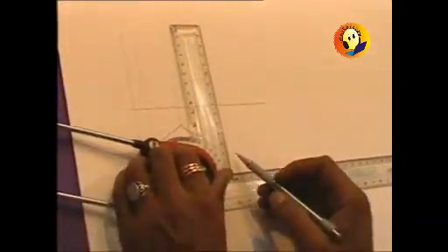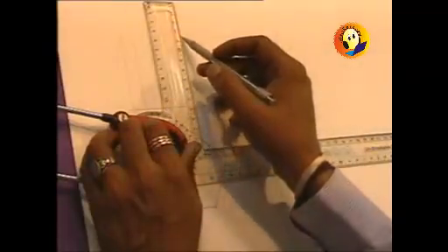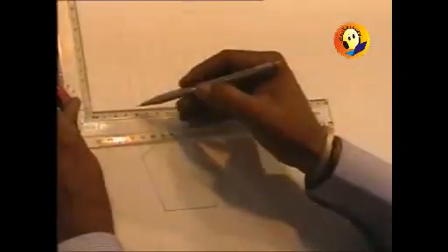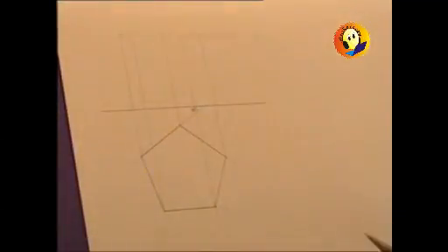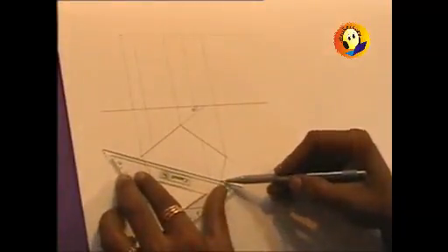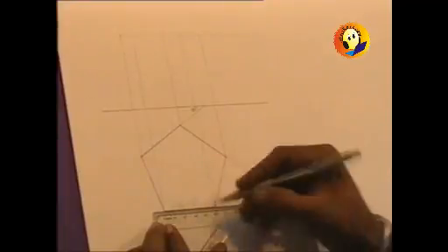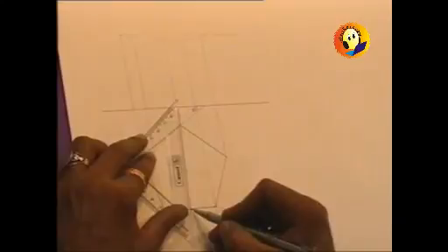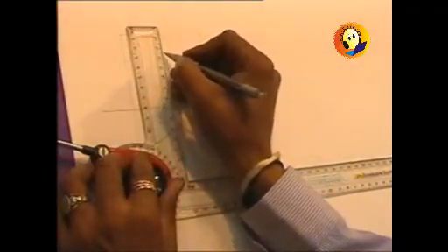So take the projectors through each point of that pentagon which is drawn in the top view. So we are completing the front view part of it. But of course front view cannot be darkened because we are required to show the cutting planes. At the same time the axis is to be marked. So let us mark the midpoint of two sides of this pentagonal shape and connect it to the opposite corner to obtain the position of the axis. As we get the axis, even that can be transferred and marked in the front view.